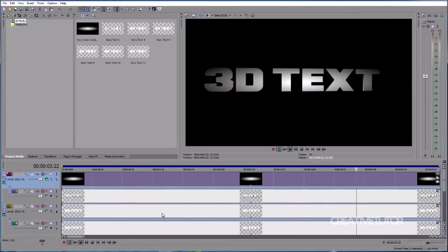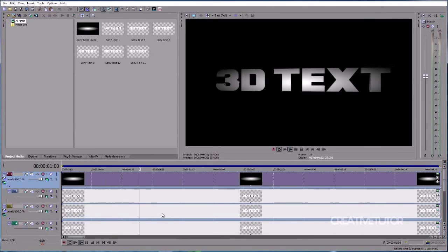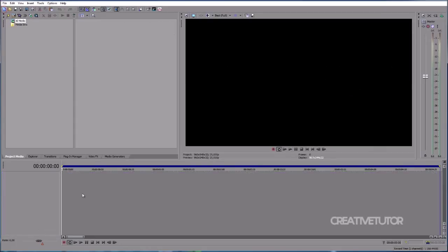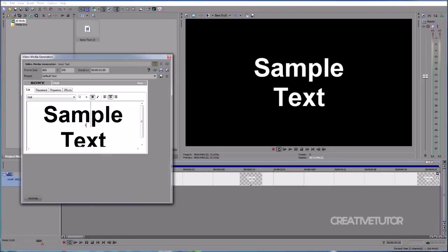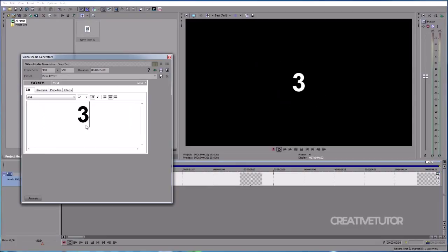And in today's tutorial I will show you how to create a 3D text intro in Sony Vegas. So let's begin by creating a new project. Let's create a new video track, and in this video track we create some text by right-clicking on the track and choosing Insert Text Media. Let's type some text. In this example I will type 3D text.